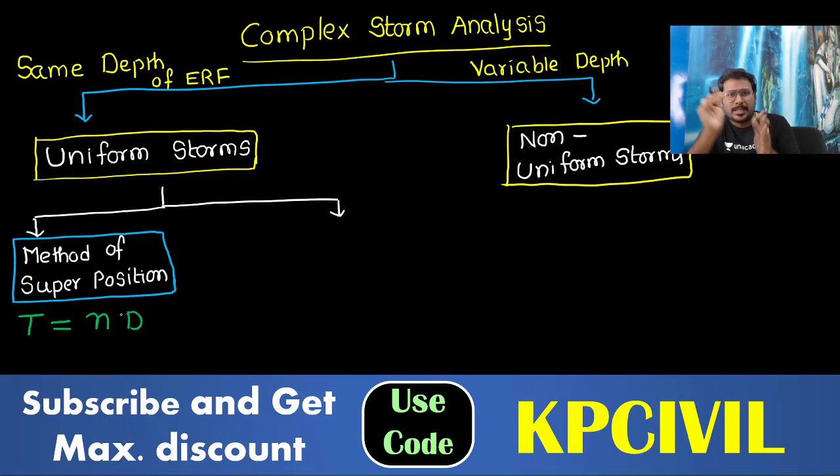For example, a 6-hour storm I have divided into 2 equal 3-hour storms, and a 4-hour storm into 2 equal 2-hour storms. That is called T equals ND, method of superposition.